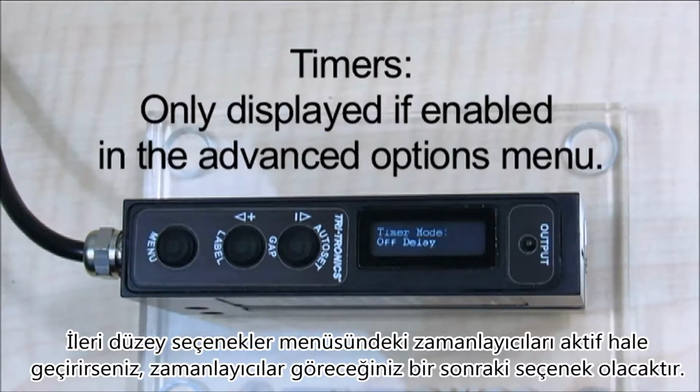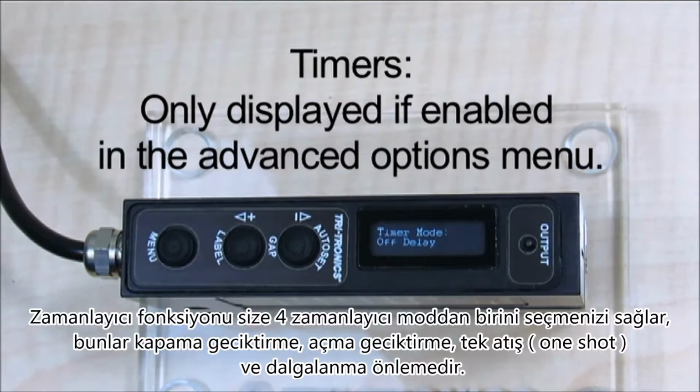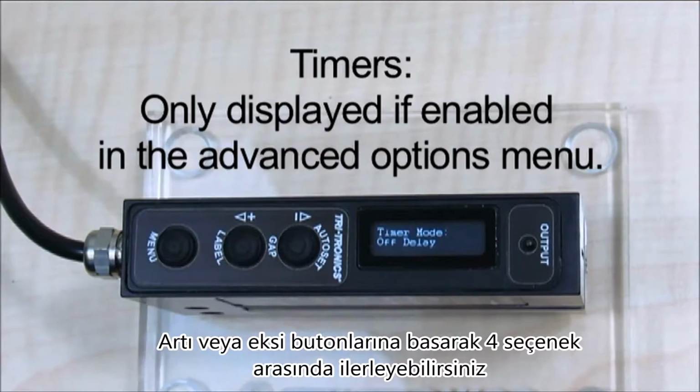If you have enabled timers in the Advanced Options menu, then timers will be the next option you see. The timer function allows you to choose one of 4 output timer modes: off delay, on delay, one shot, or debounce, by tapping either the plus or minus buttons to step through the 4 choices.